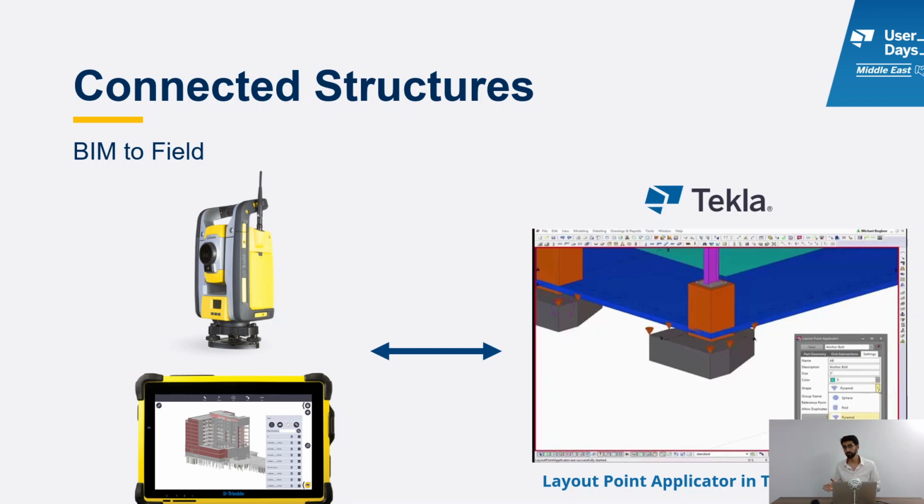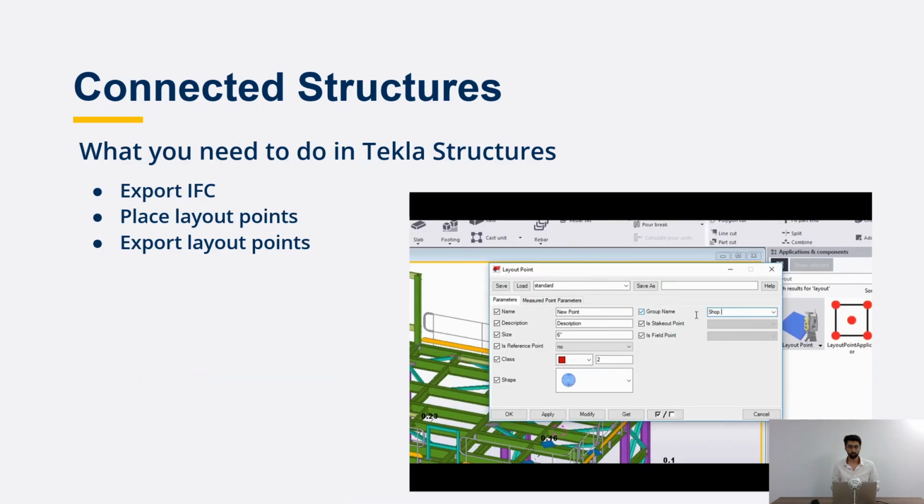And it's actually needed even in the fabrication, because sometimes you have very complex assemblies, very curved structures with little welds here and there. So doing them manually or using a traditional total station is not really going to help much. But with this technology, the robotic total station will be able to identify the exact position where you have to weld your stiffener or your secondary member, let's say, for example. Right, so let's dig deeper and see what is really required.